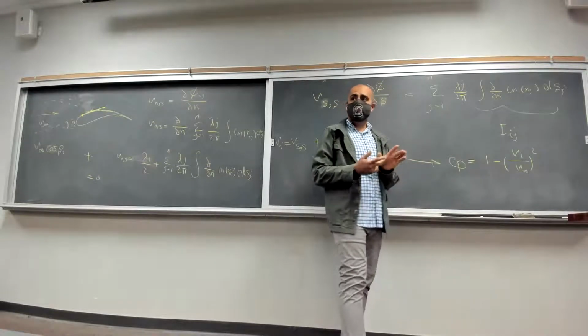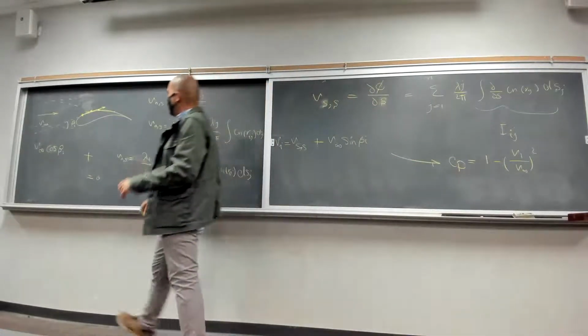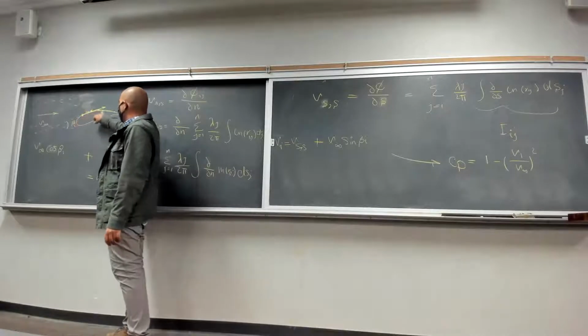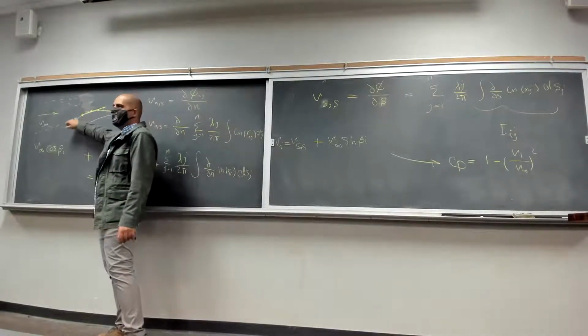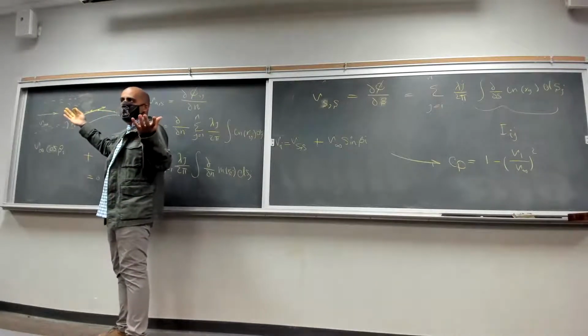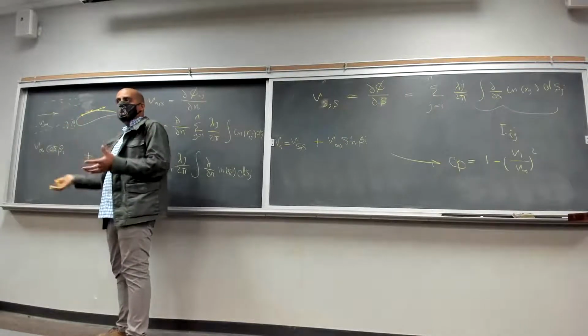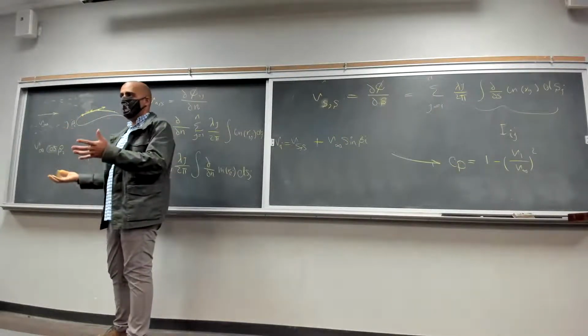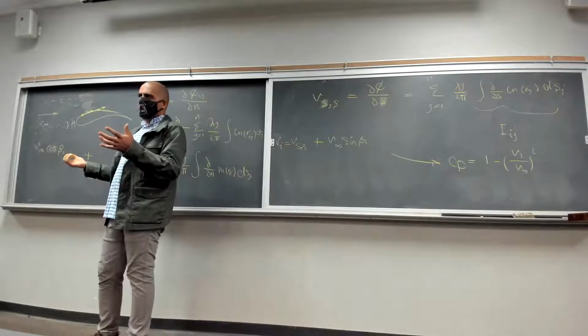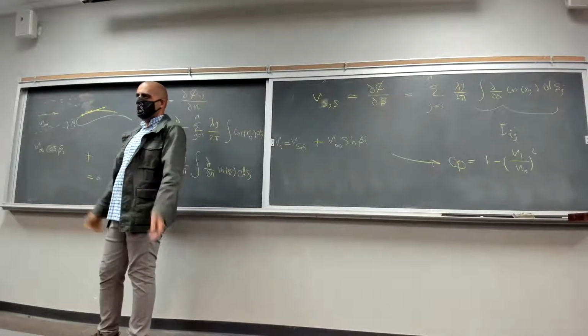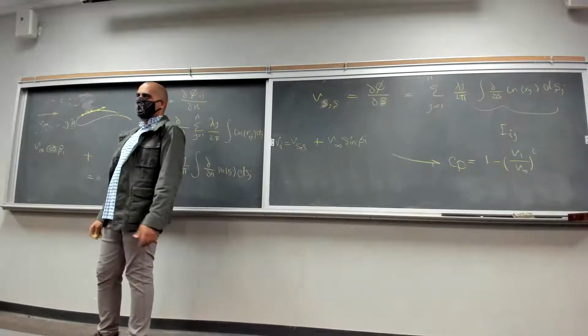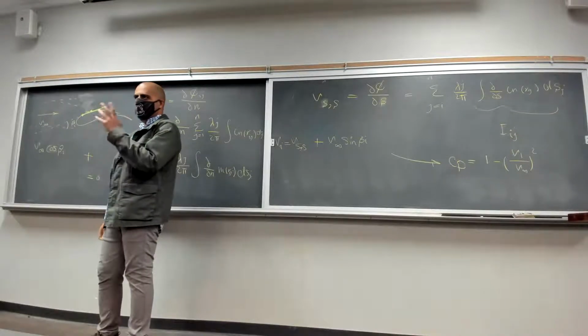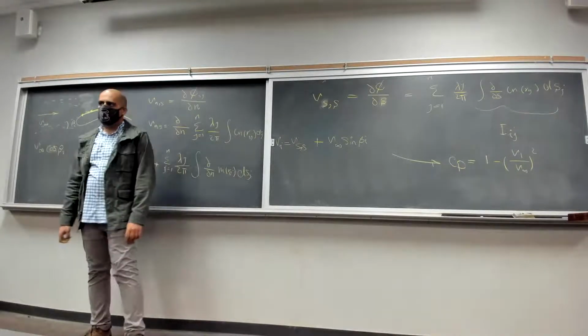When you have the pressure coefficient on each panel, you essentially have the pressure. You have the pressure coefficient here, here, here, here, here, here. You have the pressure distribution, right? When you have the pressure distribution, you can calculate lift and drag, right? What was the equation? CP upper minus CP lower, dx and dy, right? The integral of them, right?